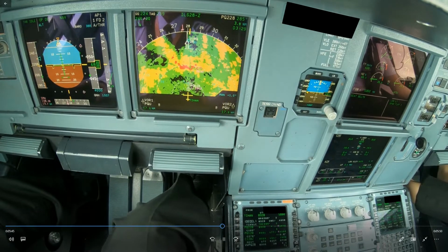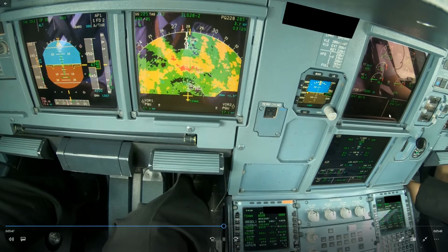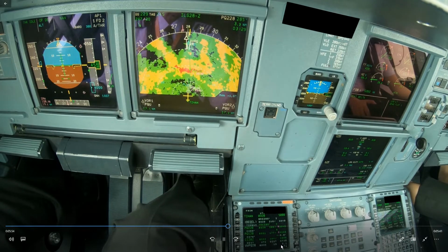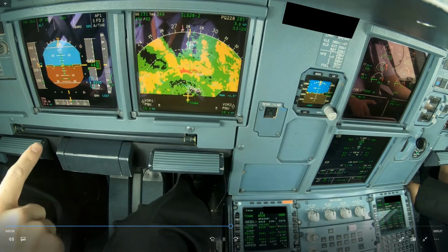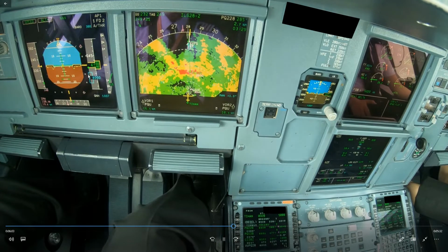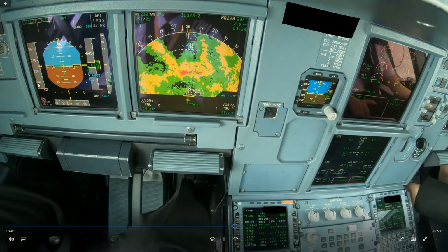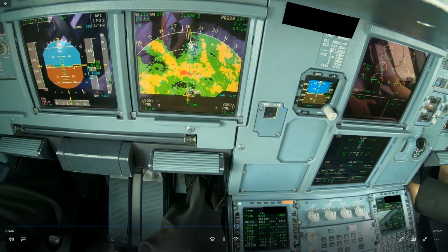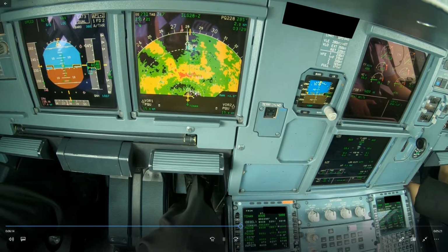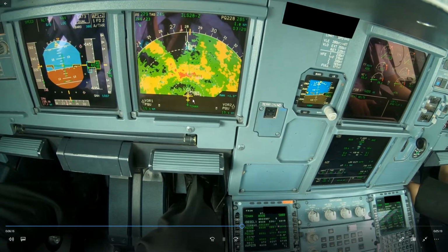Good. You can see, by the way, we have flap 3 selected for landing due to the weather. It's a bit turbulent. Okay. So next here we are approaching our cleared level again. And the same thing applies as before. If you need to descend but you can't, you need to slow down. So here it goes into Alt Star. As soon as it goes into Alt Star, reduce the speed bug to force the thrust at idle. Okay, and shortly after we can descend further. It's only a short level segment here.